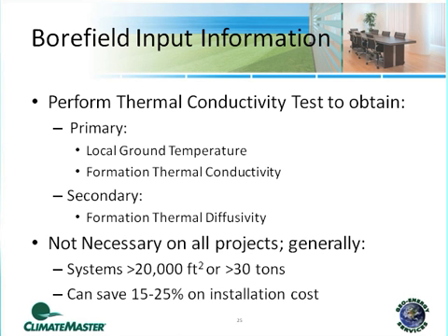Now, how do we get the ground heat exchanger information out there? We want to know ground temperature, ground thermal conductivity, and then the secondary, on some design programs, what we call the thermal diffusivity. Well, those are obviously unknowns to us, and even if we use tables, graphs, or charts, it's still kind of a relative sense. It's not necessarily concrete or absolute. So as an industry, again, back in the 90s, we came up with a procedure that's called a thermal conductivity test. This test will allow us to get these parameters, but the test costs money.